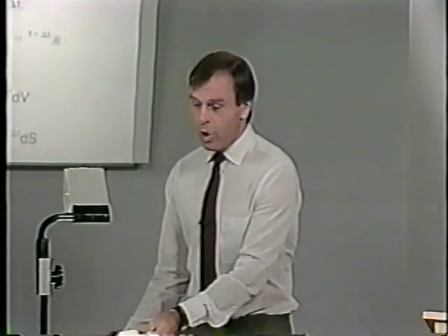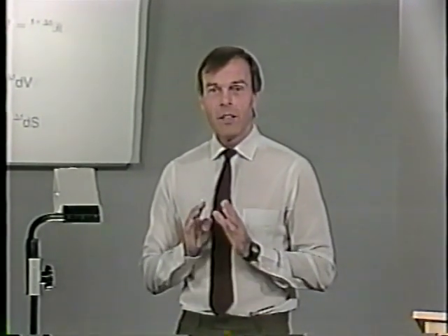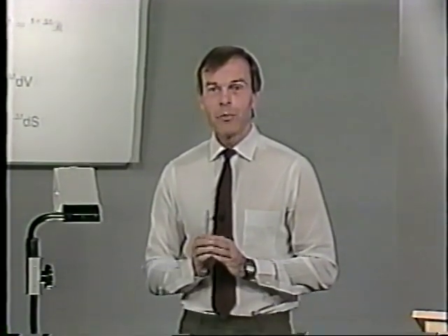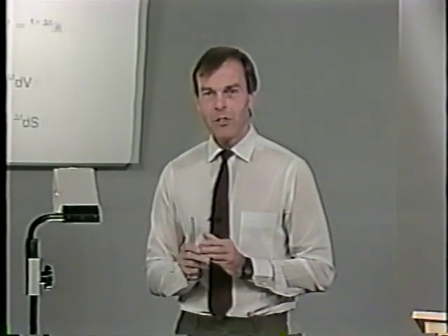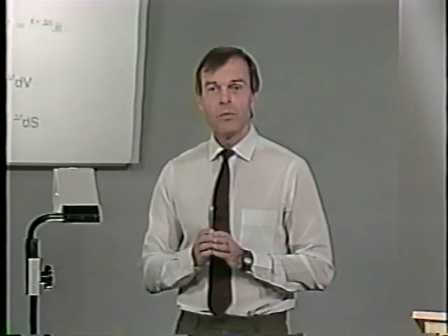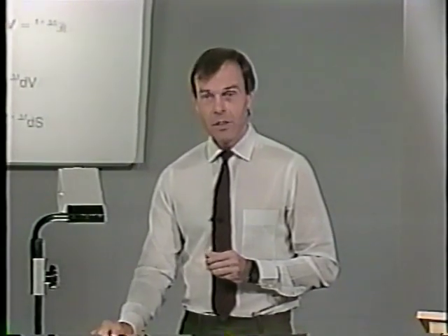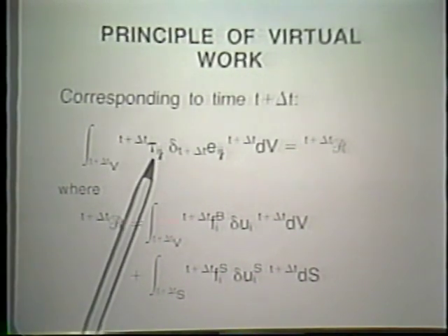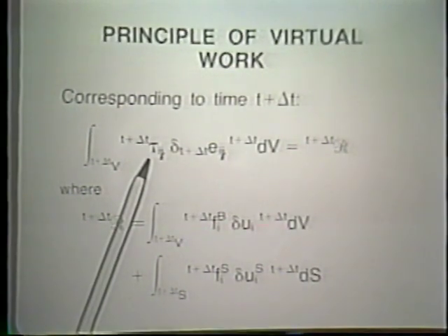Well, let us talk now then about the principle of virtual work. And now we want to look at the principle of virtual work applied to time t plus delta t. The reason being, of course, that we want to solve for the static and kinematic variables at time t plus delta t. We assume that we know the solution from time 0 to time t. We discussed in the previous lectures already the principle, and I like to now just review it once more, because it's just of utmost importance to very well grasp, understand what the principle says and how we apply it then.